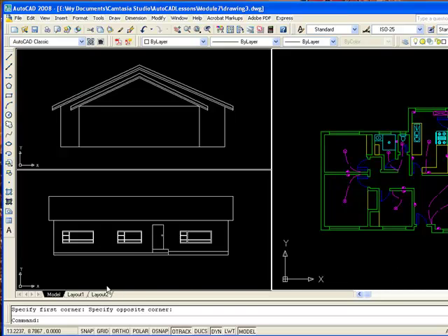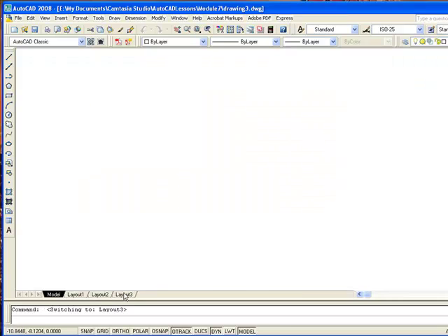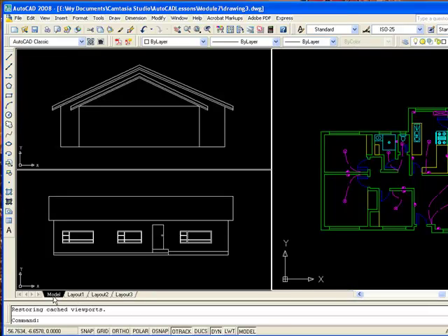If we create a new paper space or layout, Layout 3, you will see it has not changed. It is still in its original coordinates. You can also create viewports in the paper space layout, but you must remember it's a bit more tricky, and it's going to take all 3 models here. Viewports can be saved, named, restored, deleted, joined, as well as plotted.